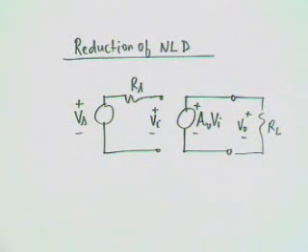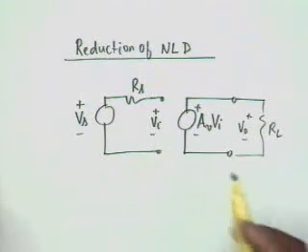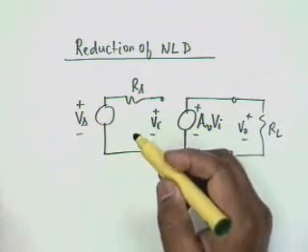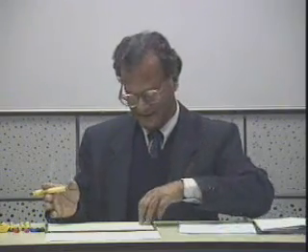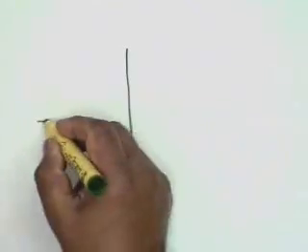Now, you know from your experience with voltage amplifiers that we have discussed so far, that this ideal relationship between the output voltage and the input voltage, that they differ only by a constant, that their ratio is a constant, this can be valid only over a certain range of input voltages. Agreed? As soon as you go into the saturation region or in the cutoff region, nonlinear distortion starts, and therefore, if I plot the curve of V0